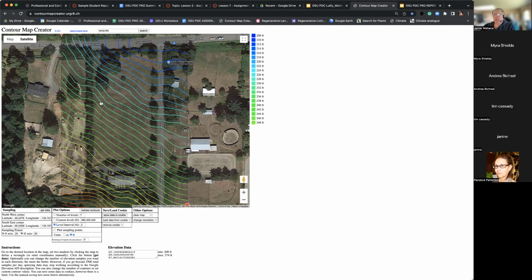Well, you'd want to have a scale reference, right? Mm-hmm. And I don't believe Contour Creator provides a scale to it. Now, when you're capturing from Google Earth, it does. But in the absence of that, if I was taking a screen capture here and I wanted a scale, all I'd have to do is measure a fixed element that's on the screen here.